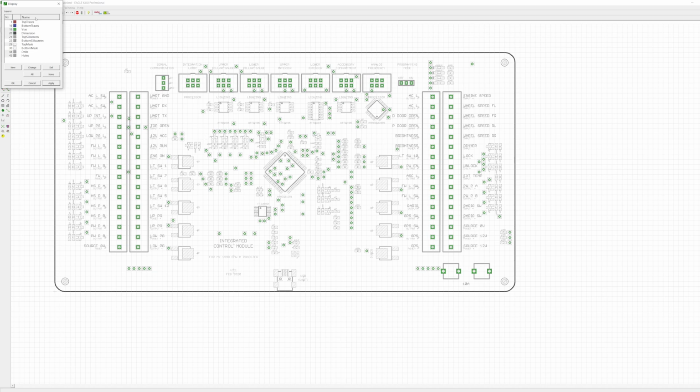If you look at the top left, you can see that I'm not using that many different layers. Like I mentioned, the red and the blue are the top and bottom traces, the copper that connect point A and B. The vias, that's basically a drill hole that has metal inside the center of the hole, and it connects the top and bottom layer at that point, shown in green here on the board.